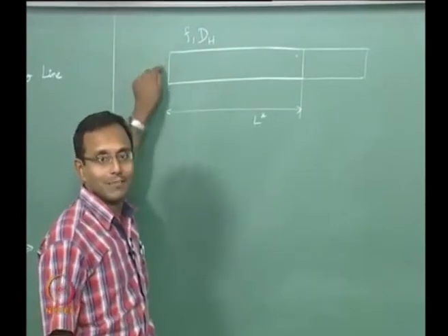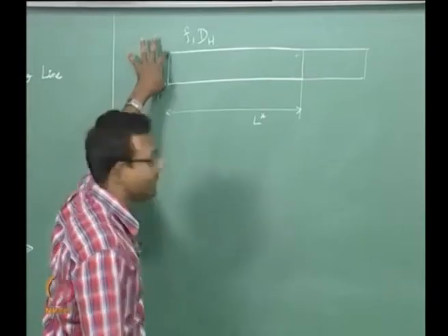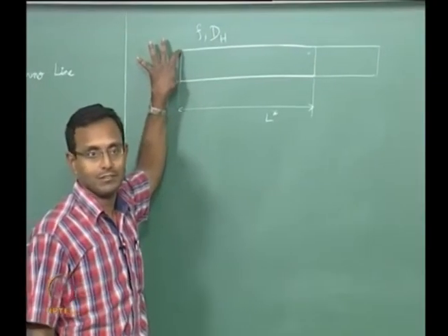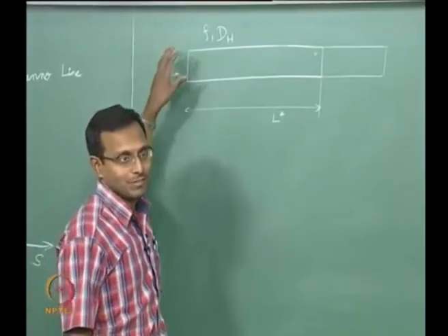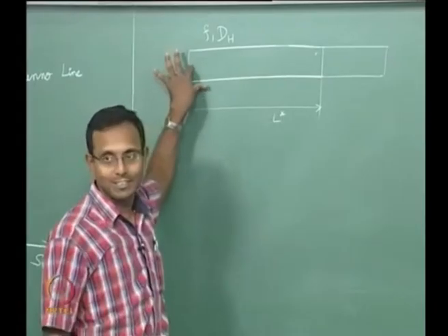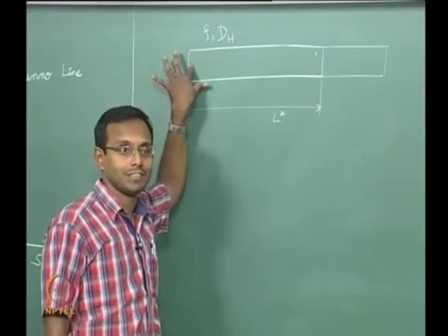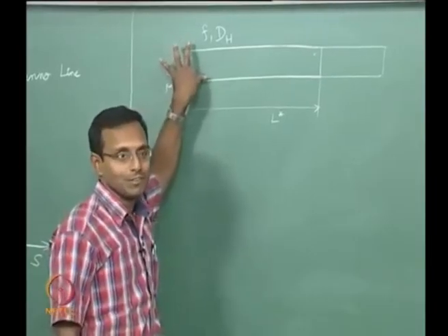It will go and change the inlet Mach number. So what will happen overall? My flow velocity at the inlet is going to be lesser. Density also will be adjusted accordingly based on the Mach number. And finally I am going to have a mass flow rate that is lesser. A mass flow rate that is lesser, what will be the final situation?